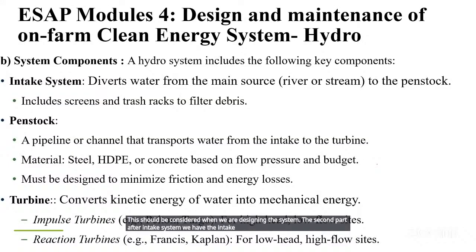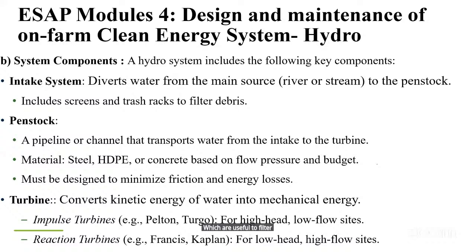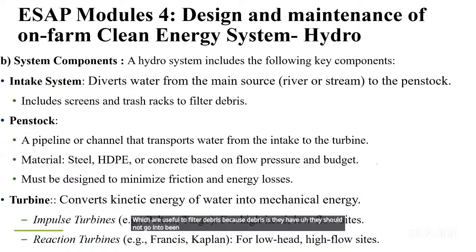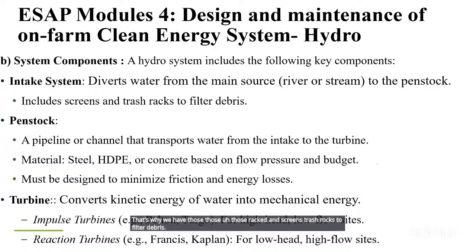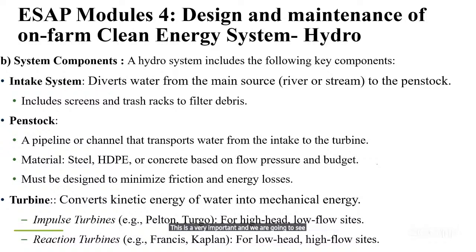Intake system, which is coupled with screens and trash racks, which are useful to filter debris. Debris should not go into the penstock, because if it does, it will end up creating problems for the turbines or the whole system. That's why we have those racks and screens, trash racks, to filter debris. This is very important, and we are going to see that it should be maintained when we reach